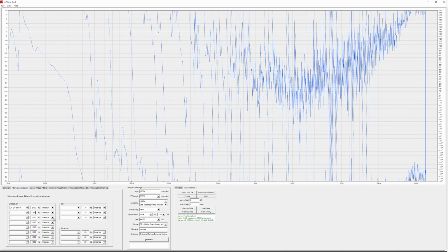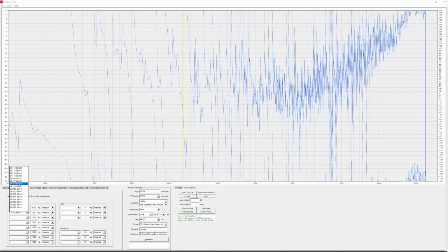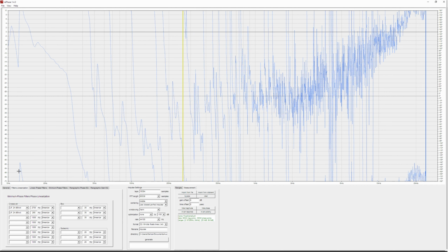Which divides the audio signal frequencies between the woofer driver and the mid-range driver. I don't have information on the type of this filter, however it seems to be most flat at 12 dB per octave. 24 seems to be too much.